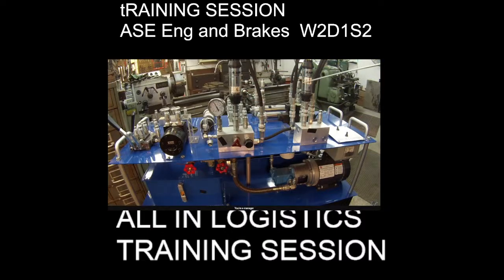Alright, where is that fluid going? It's going over this relief valve right here and going back into the tank, through this filter back here. So the only way you see fluid right here is when I actually actuate this cylinder and make the cylinder go in and out.